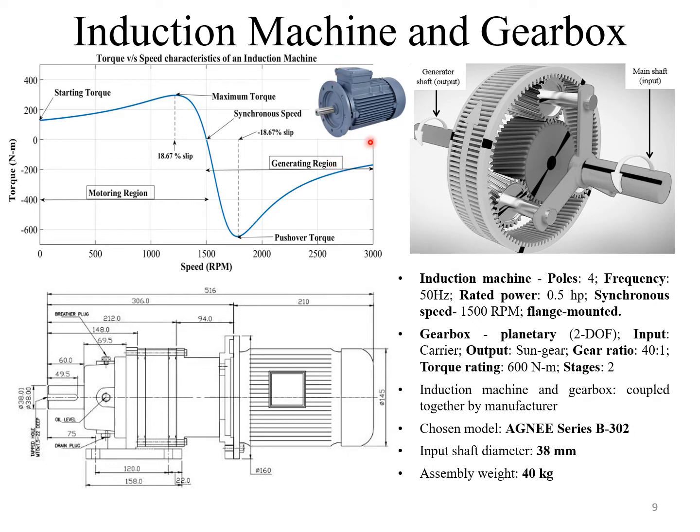In this project, three-phase, four-pole induction machine is chosen. As the machine is directly connected to the main supply, the operating frequency is 50 Hz, making the synchronous speed as 1500 rpm. A typical torque speed curve is shown, where our region of interest is the negative slip region, where the machine behaves as a generator.